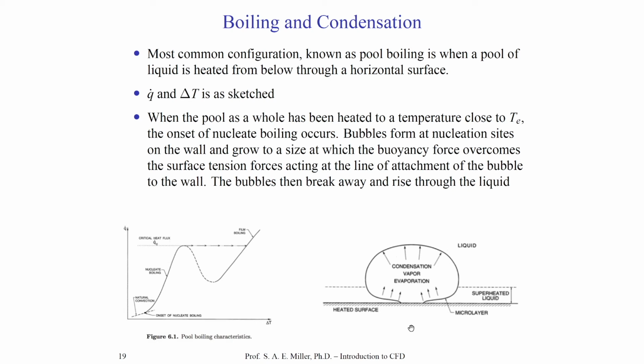This is observed through this nucleation process in the lower right. Here, we have a heated surface, which might be, of course, your pan, and the water exists inside the pan. This little vapor formation will form at the nucleation site, in the layer of superheated fluid. So this is a formation of a multi-phase flow with heat.